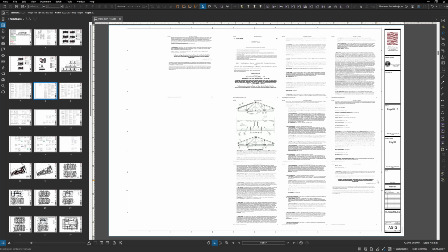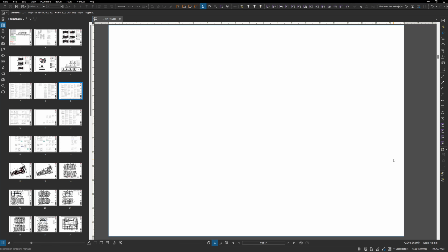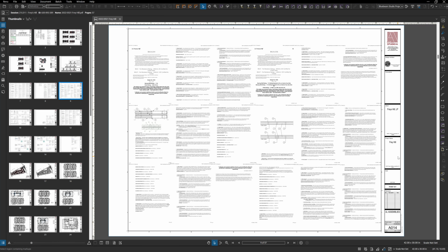The drawings are in the order that they're in because the most important information in my mind typically comes first. So don't shy away from these things. Make sure that you got them in there correctly. Make sure that they are legible, that they can be read, and make sure that we're trying to do our best to label these sheets correctly, so that you are clearly communicating to the contractor what's in it and what you want them to build.